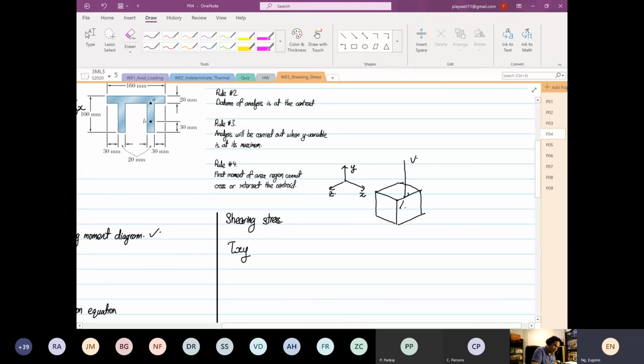Sorry, I shouldn't have done that, it made it messy. We are looking at the shear stress in this direction. So this is shear on the X plane in the Y direction, and this will go opposite. Over here, this will be your shear in the Y X direction. And we know that shear XY is equal to shear YX.